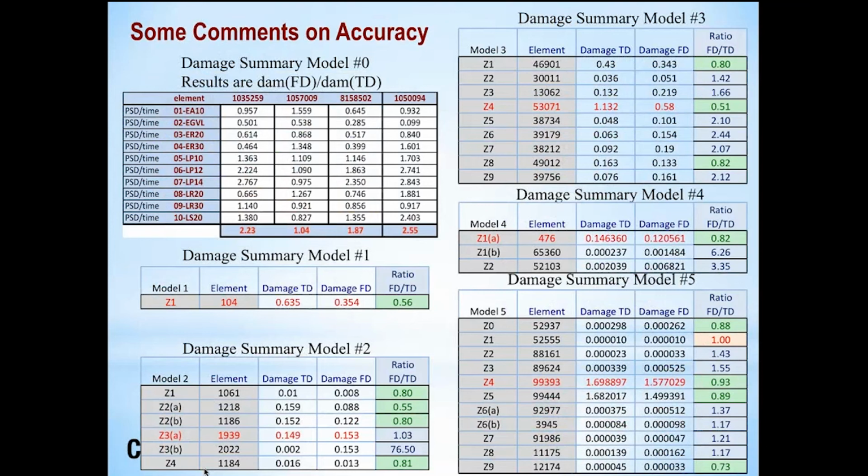We've had a lot of people repeating this since then because they didn't believe that you would get the same kinds of results. Now, by the same kinds of results, we typically talk about anything less than a factor 2 difference in damage. We talk about that being the same result, because for a difference in factor 2 on damage, you only need a 6 or 7% change in stress. So we're typically looking for a level of accuracy within that factor 2. And furthermore, when we see a difference, it's not possible to simply say, the frequency domain had an error, because sometimes it's the time-based result that's wrong. In particular, we looked at 1 or 2 of these differences here, and when we looked into it, we found that the problem was caused by the fact that the frequency domain was incapable of going to sufficiently high frequency